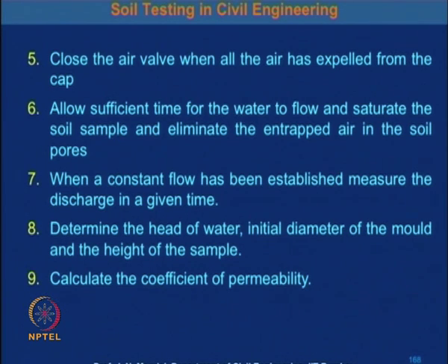When a constant flow has been established, measure the discharge in a given time. Then determine the head of water, then the initial diameter of the mold and the height of the sample. And then you can calculate the coefficient of permeability of the soil.